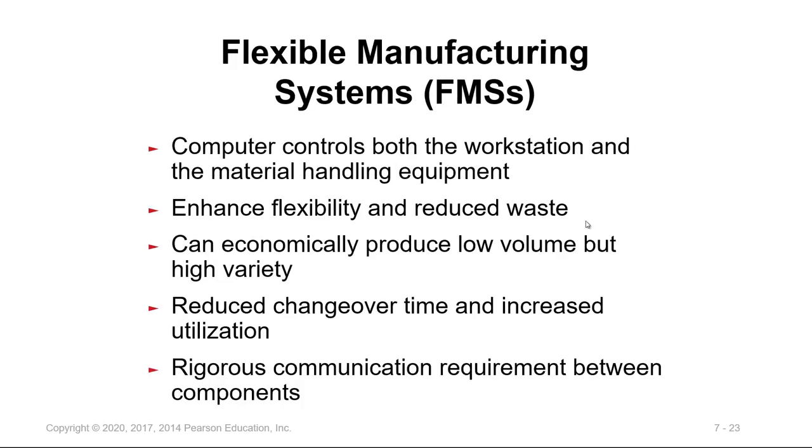In flexible manufacturing systems, computer controls both the workstation and the material handling equipment. So the FMS can enhance flexibility and reduce waste. It can economically produce low volume at high quality. It can reduce changeover time and increase utilization. It has strict communication requirements between the different components.